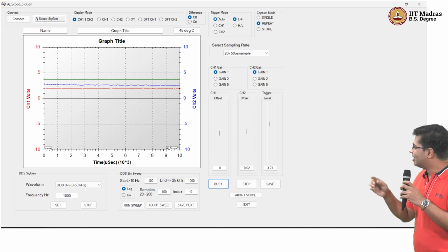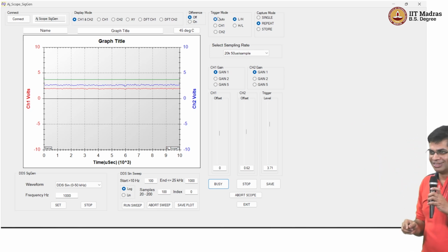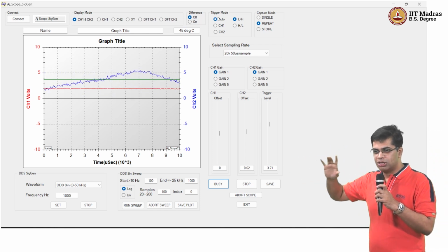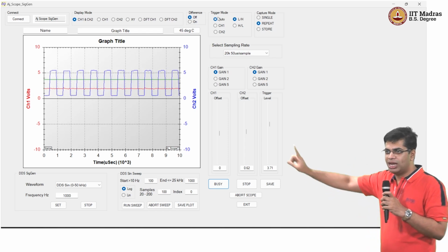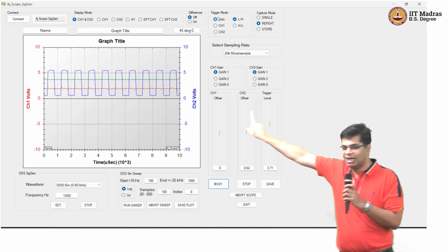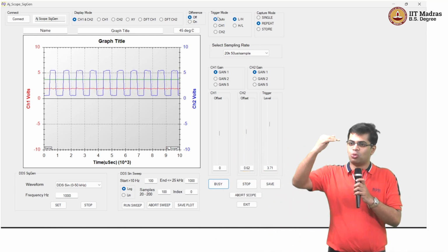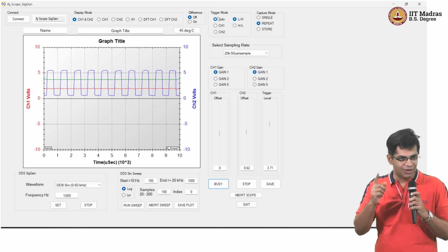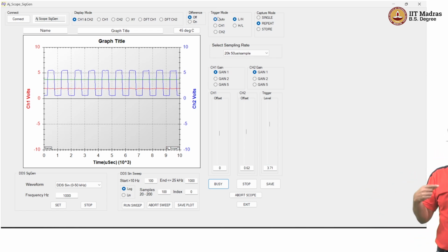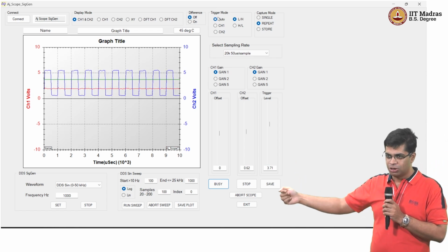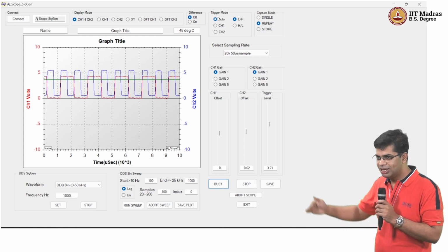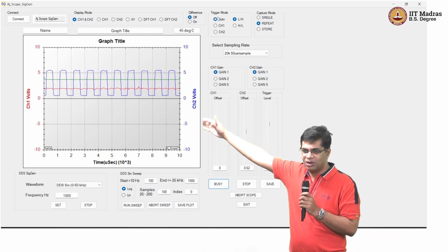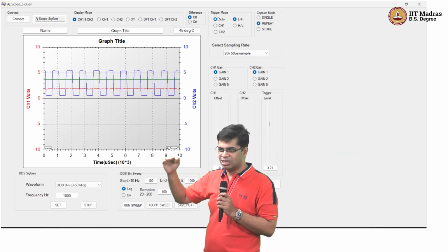And what the store mode does is that it allows you to capture one set of data using the single mode. It does not clear the canvas. It then puts one more trace using another single mode and another single mode. Given the fact that your input can very nicely be triggered using the clock, you can build up your entire counter data of 4 bits or 5 bits or 16 bits just by using the store mode.